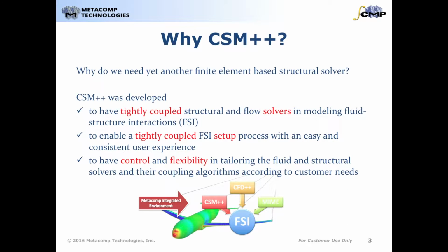Why do we need yet another finite element-based structural solver? CSM++ was developed for the following reasons: to have a tightly coupled structural and flow solvers in modeling fluid structure interactions, to enable a tightly coupled FSI setup process with an easy and consistent user experience, and above all, to have control and flexibility in tailoring the fluid and structural solvers and their coupling algorithms according to customer needs.